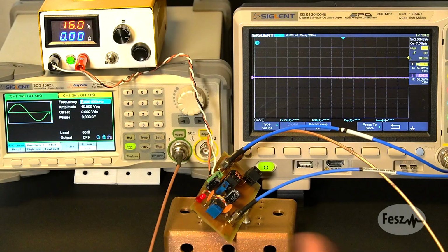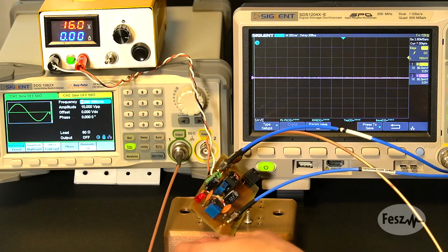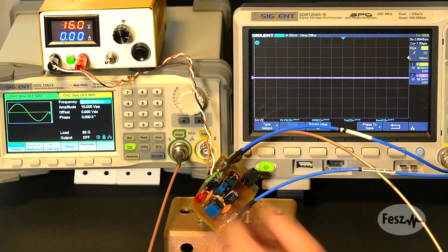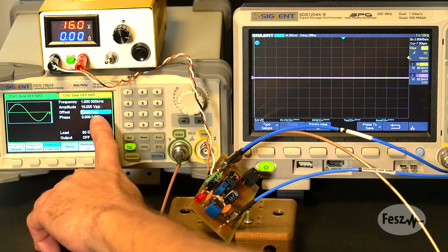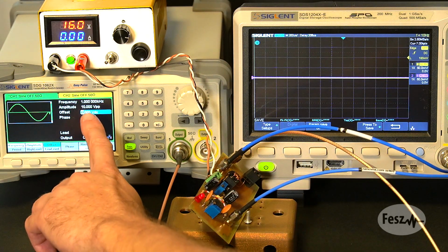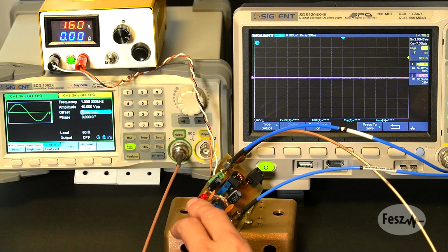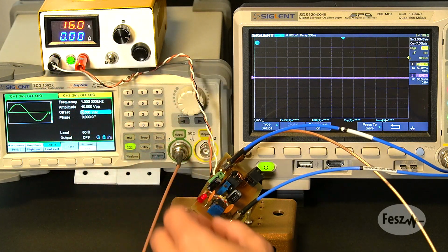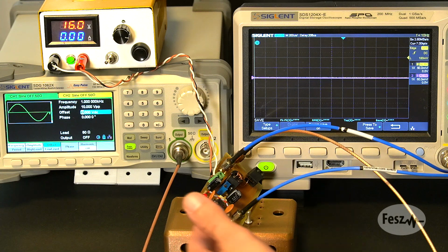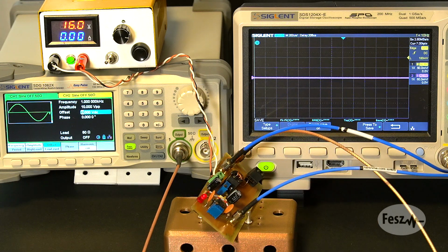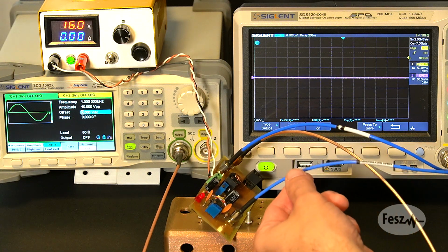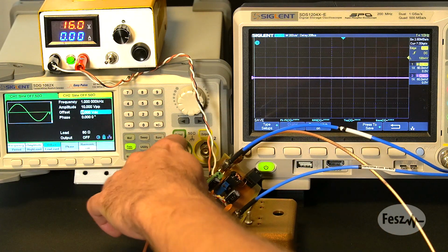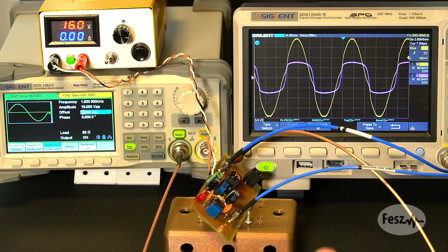So, to finally test this thing, I assembled this setup. So I have my signal generator that is driving the board. I set this to 1 kHz and the amplitude we will play around with. Then the board is also supplied from the power supply to supply the integrator. And then the output is being displayed on the oscilloscope. So I have the current measurement and the voltage measurement.